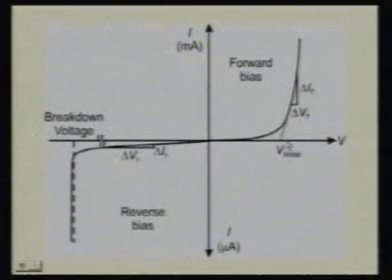After a particular voltage, which is V knee, also known as the knee voltage, the cut-in voltage, or threshold voltage, if we increase voltage beyond V knee or V cut-in, then current increases very sharply. And in the reverse bias condition, we increase the voltage in the reverse direction and measure current in microampere or nanoampere, depending upon which kind of diode we have taken, which kind of materials we have used in making diodes. So we see that the current is very small, few microampere or few nanoampere only.